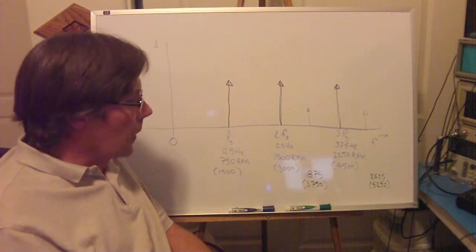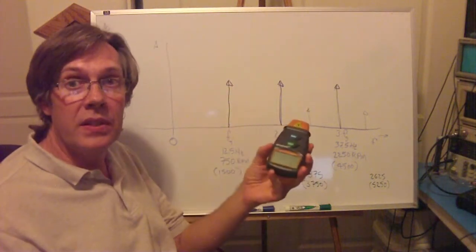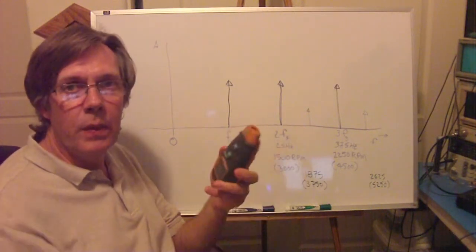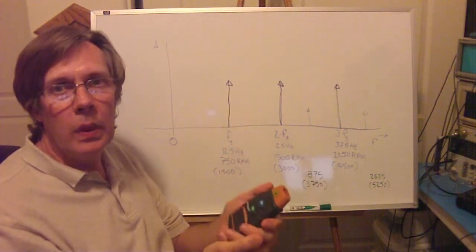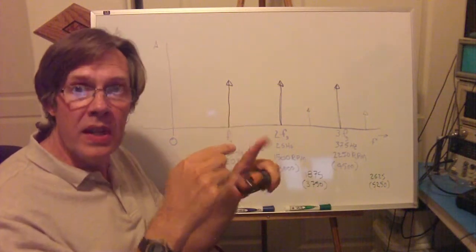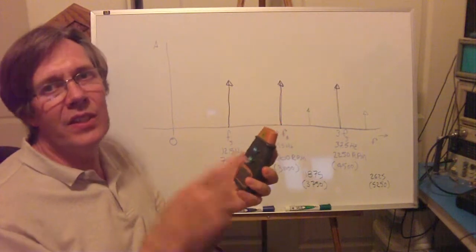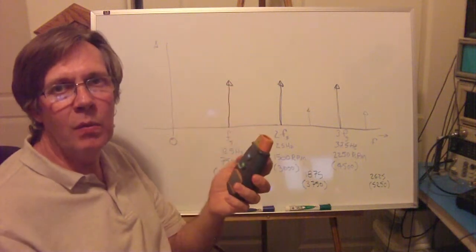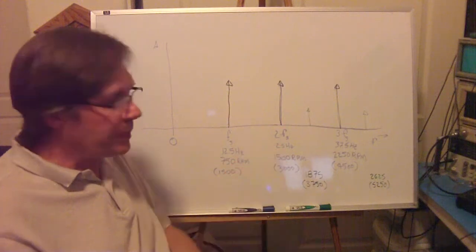blade. We have a little device here that we're going to use in the next demonstration, which lets us measure the rotation rate of the blade. It sends out a little infrared beam and looks at the reflections coming back, and that's why we put a reflector on one blade. And we have actually one on the underside of the blade too. But unfortunately, this thing's sensitive enough that it still sees both blades. Even though there's a reflector on only one, it gets a reflection from both blades. And so it reads twice the frequency that it's actually turning at.